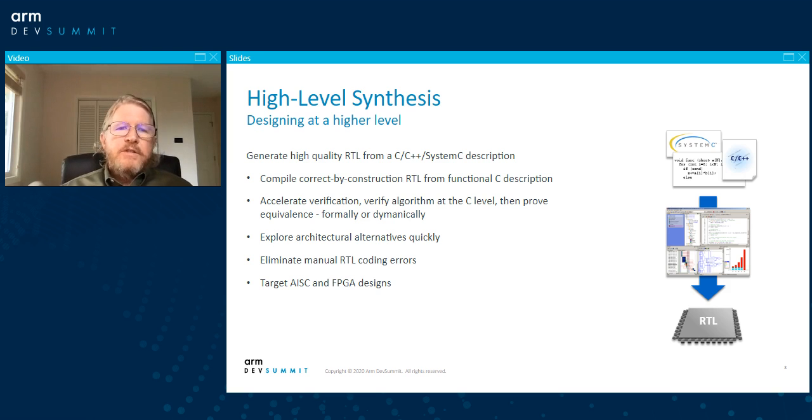And finally, high-level synthesis gives you independence from your target technology. It can be targeted either at an ASIC or an FPGA. And it does it in a way where we do not have to describe exactly what will end up in combinatorial logic between register stages. That will be a downstream process, part of the compilation, and that makes retargeting the algorithm much easier.